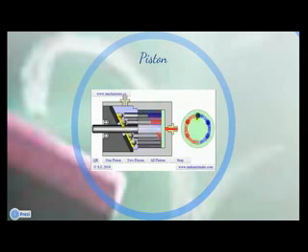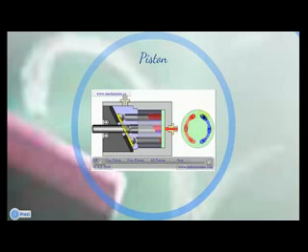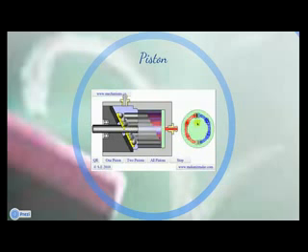In future videos, we will represent hydraulic pumps and motors with the green port plate disc shown on the right. But how can we tell whether a port plate disc represents a pump or a motor just by looking at it? Unfortunately, we can't, since we don't know whether the piston is moving toward the port plate or not. To overcome this, let's make one more convention.